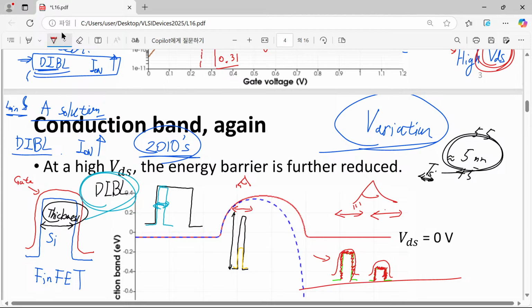However, let's say, oh, I love it, so why don't you make it just 1 to 100 aspect ratio, then we can have a super powerful transistor. Yes, you can try, but eventually your device will have zero yield, because your tall fin eventually collapses or merges with each other. That will be a nightmare. So that's the reason why there is a certain limitation of this aspect ratio.